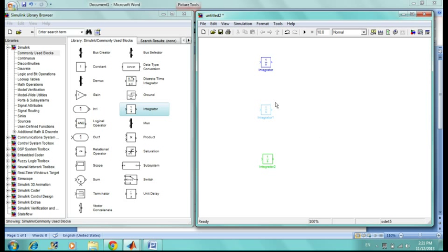Now you can also change the names of the integrators in order to make it easier to see which integrator is responsible for that specific ordinary differential equation. This can be done easily just by clicking on the integrator. Just change the name to dCA/dt. Same thing for the second one, just dCB/dt. The last one, dCC/dt.